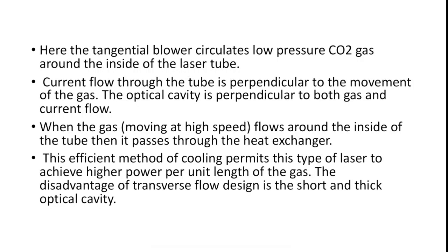TEA design. TEA stands for transverse excitation at atmospheric pressure. This design is considered a variation of the transverse flow design. With this design, the gas that flows around the inside of the tube is maintained at near atmospheric pressure. This high density gas flow allows extremely high power outputs. However, it is very difficult to maintain ionization of the gas when the gas is at high pressure. Generally, the voltages required to maintain this type of operation are extremely high. That is why the TEA design laser can only be operated in pulsed mode. The beam diameter of this type of laser varies from 5 to 10 millimeters.